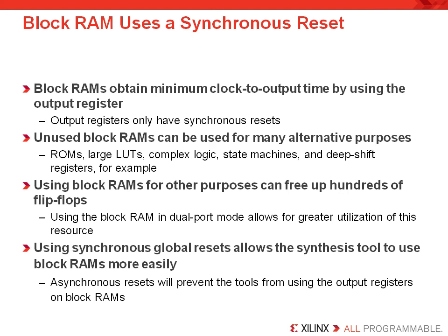Also keep in mind that the easiest way to get the block RAM is to build it with a core generator and then instantiate the core into your design. Now, this is very commonly done because most synthesis tools will not infer the less obvious block RAM functionality.